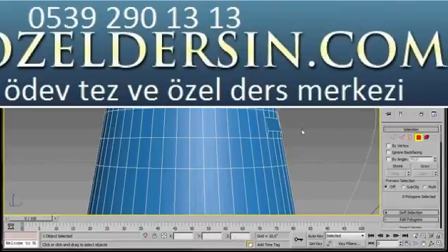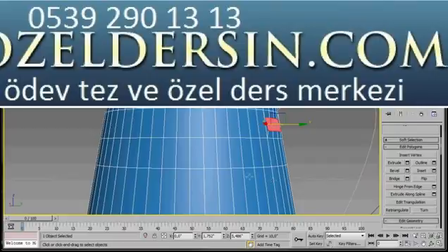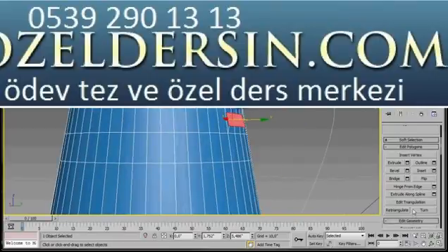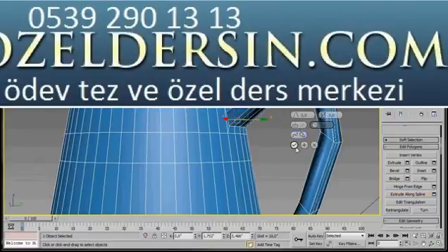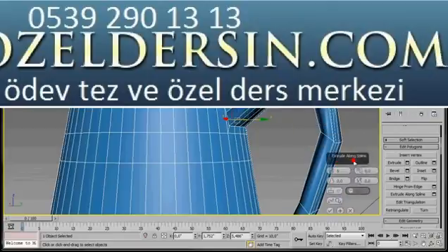Then let's go over to the panel. And here under Edit Polygons, we'll scroll down and click on Extrude Along Spline. Click on the small settings box. Okay, let's have a look in the caddy. We're just going to scroll down and click on the button that says Pick Spline. It's this one here right at the bottom. Click it, and then we'll come over now and click on our line. There we are, look, automatically our handle's been created, but don't accept it yet.